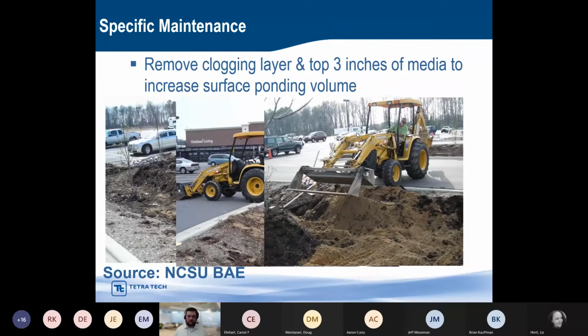That tends to hold up for much higher flows. We generally get more like 3 feet per second with seed. It can go higher than that if we're using turf mats. I think with turf matting, you can go up even to about 10 feet per second on the velocity coming through there. So those are good alternatives. But river rock can definitely work. But you do lose a little bit of that function of the mulch. So the mulch helps retain that moisture for the vegetation, and also can absorb some types of pollutants. And so river rock can be an acceptable alternative, but you do lose a little bit of that water quality or pollutant removal function.